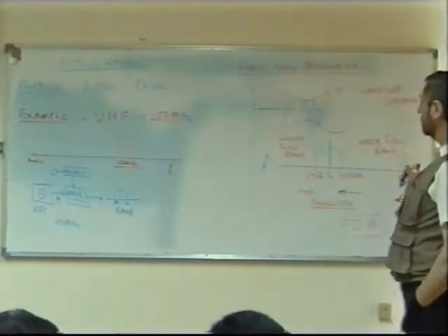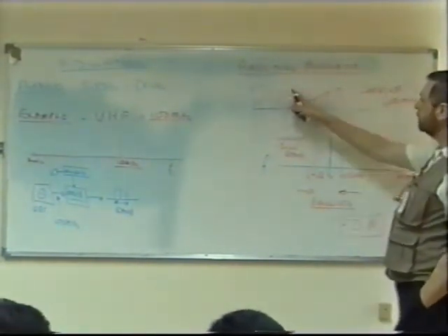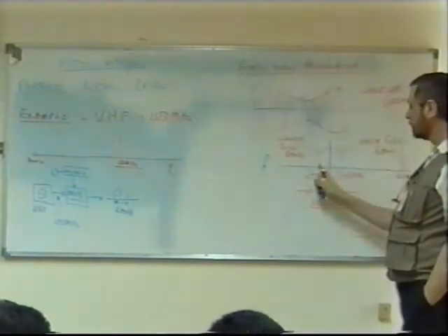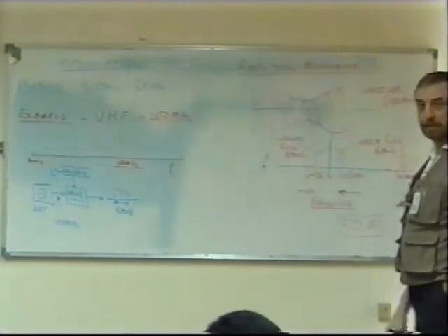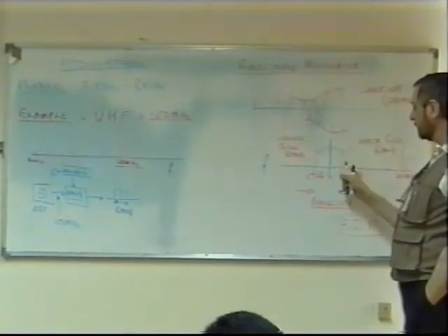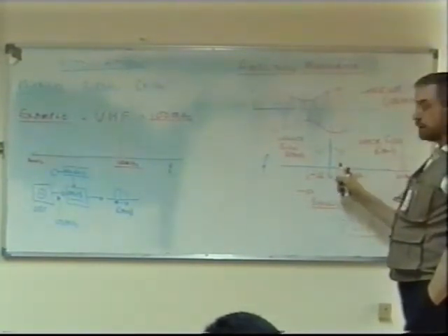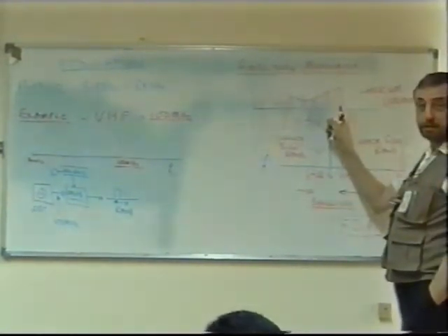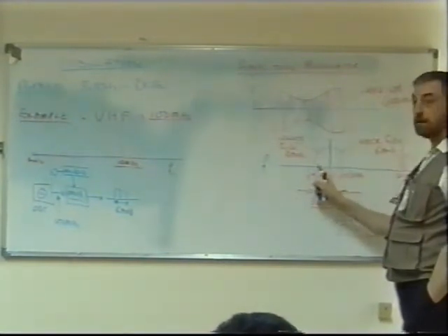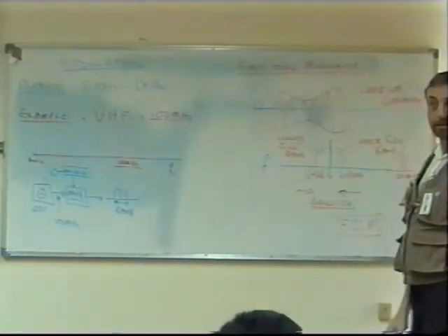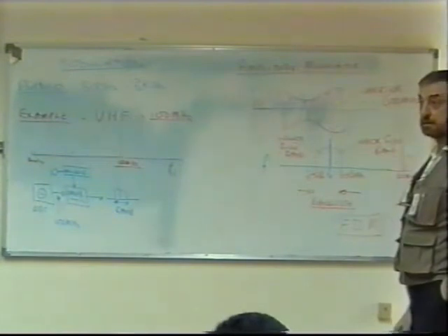But this is an example of FDM. But remember that in amplitude modulation, we produce upper and lower sidebands. The upper sideband is the carrier plus the highest frequency. The lower sideband is the carrier minus the highest frequency, whatever that is.